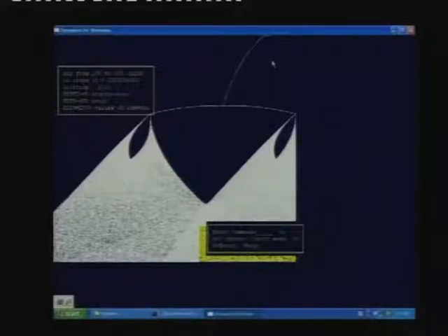Yes. So, from here a period 1 orbit starts, and the parameter, in this case the load resistance, has been varied from 100 ohm to a total of 600 ohm. So, up to say something like 300 ohm, it was a period 1 orbit. So, there is a range of the parameter load resistance for which the periodic orbit remains. And at this point what has happened? It is a smooth period doubling, a normal smooth period doubling.